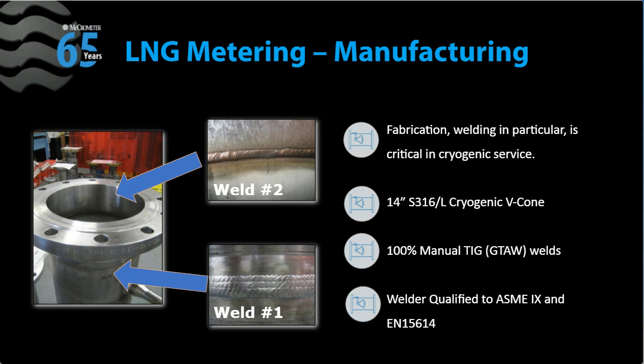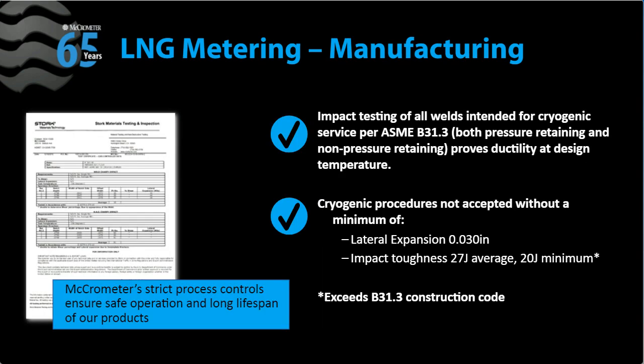Manufacturing for LNG applications is very stringent. So impact testing of all the welds intended for cryogenic service per B31.3 proves that ductility is at design temperature.